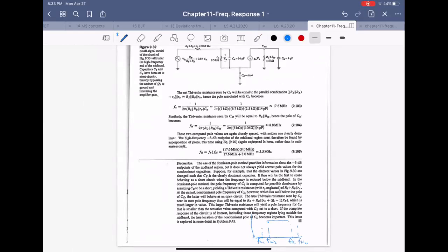And this is the midband gain. Connect this one, 20 dB per decade, 40 dB per decade, 20 dB, 40 dB per decade. Then make a smooth curve, 3 dB below the midband gain at the corners, like that. And we make a curve like this.